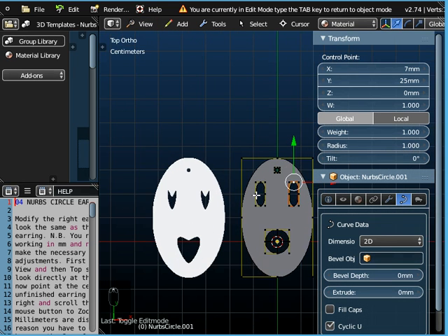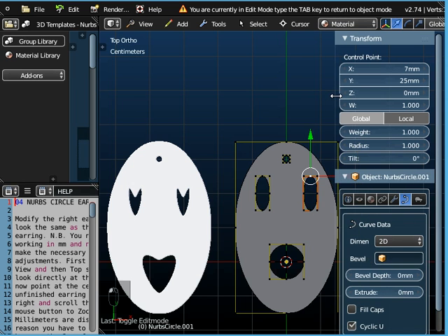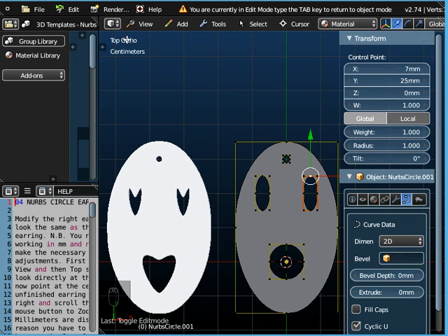And you'll see when we do that, and I'm just scrolling the center mouse button, now we really truly are looking down from the top of the object. So that's something to take note of. If you're in perspective mode, switch it across to ortho. You can work obviously in perspective mode, but we genuinely think it's a little bit easier in an ortho mode.